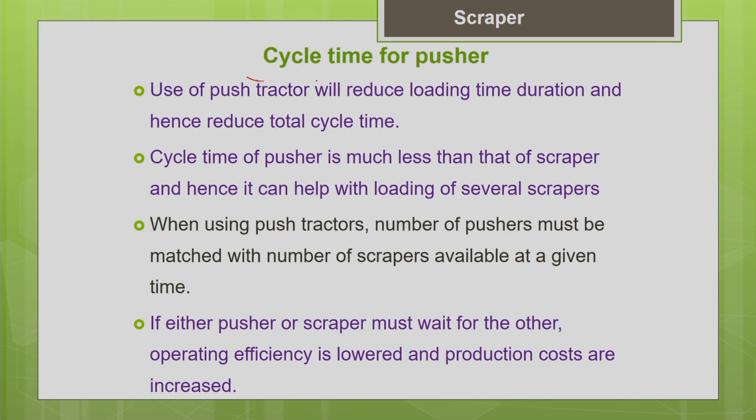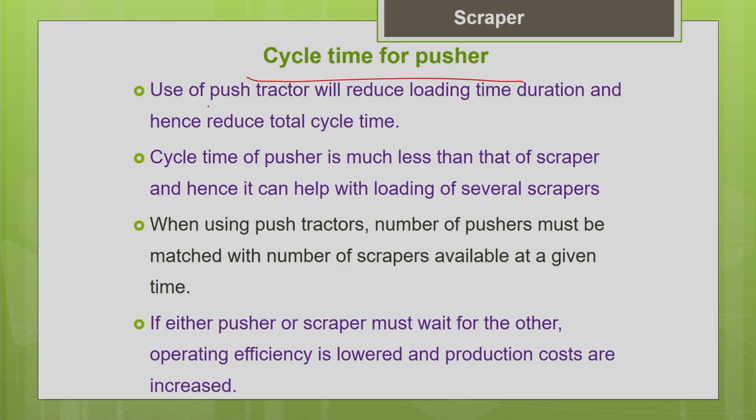Now let us see how to estimate the cycle time and what are all the components of the cycle time of the pusher. As we discussed earlier, when you use a pusher for assisting the scraper, you can reduce the loading time of the scraper. It will help you to increase the productivity of the scraper and reduce the unit production cost of the scraper. So use of a push tractor will reduce the loading time duration and hence reduce the total cycle time.